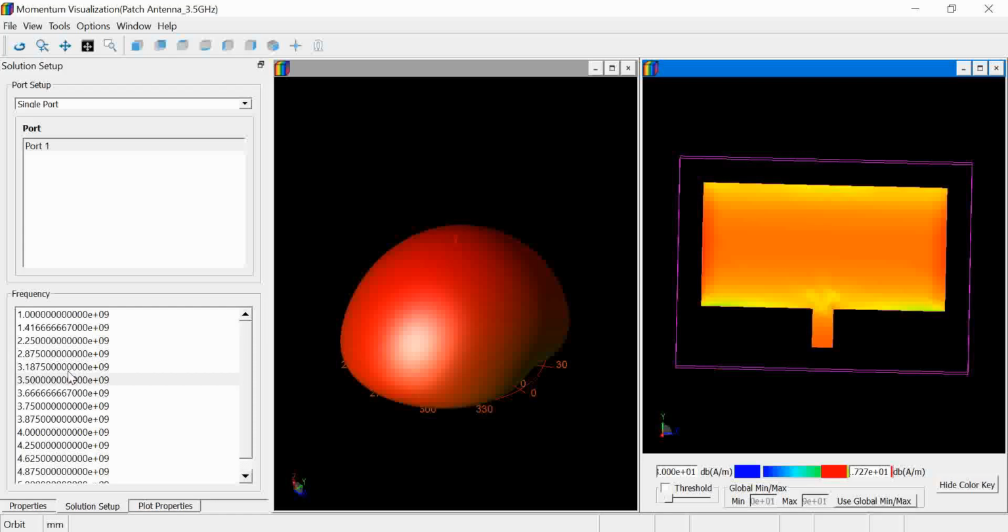I hope you understood how to calculate the S11, how to go about the designing part, how to generate the surface current, and how to look for your key parameters. If you have attended our previous course, which was in live mode, you can even compare your antennas with 2-3 softwares which use different computational electromagnetics techniques. One is using FEM, one is using FDTD, one is using MoM. In this way you will be able to analyze all your antennas.